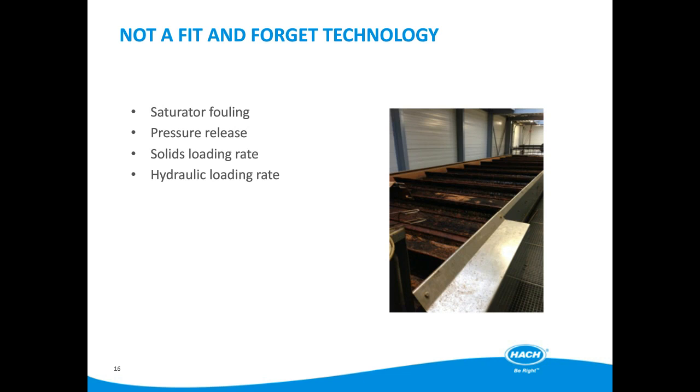Firstly, the increased flow and hence reduced residence time in the floc tank will result in the floc not being fully formed. Secondly, even if the recycle rates can cope with the increased hydraulic load, the water will not spend sufficient time within the DAF tank for the bubbles to rise to the surface and remove the floc and solids. This will result in poor solids removal and hence poor DAF efficiency and effluent quality.